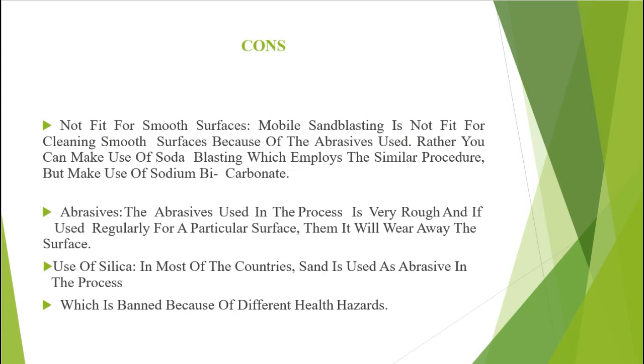Cons. Not fit for smooth surfaces. Sandblasting is not fit for cleaning smooth surfaces because of the abrasive used. Rather, you can make use of soda blasting, which employs a similar procedure but makes use of sodium bicarbonate.